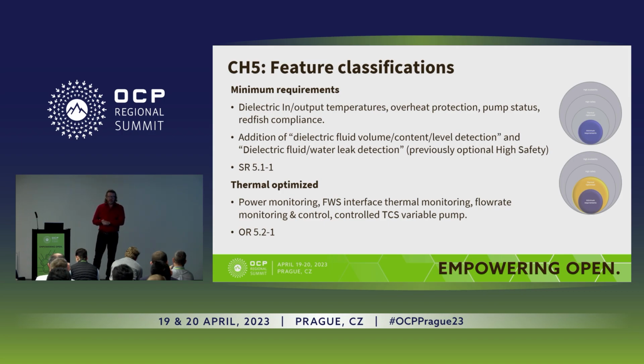We've added to the minimum requirements, or we are adding, I should say, dielectric volume, content, and level detection. So there is a way to monitor how much fluid is in a solution, but also dielectric fluid or water leakage detection. If there is a leak, it should be detected. That used to be a high safety requirement, an optional one. The current proposal is to move it into the minimum requirements and to make it mandatory for any kind of technology.